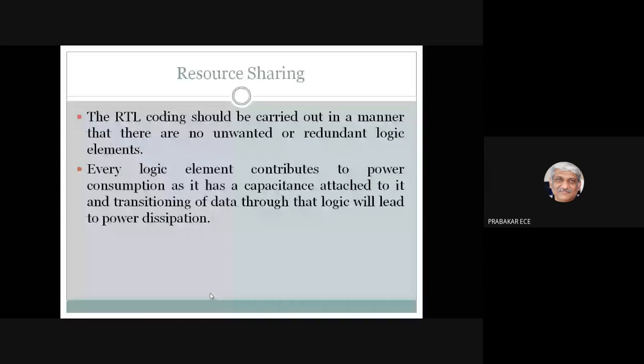And every logic element contributes to power consumption as it has some capacitance attached to it. I think you should know, right? Every line, every track will have an RC component. The resistance and capacitance will be there. The power consumption will always be there. And this capacitance can be considered low in some cases, right? So by having resource sharing, you can reduce the size of your device or your circuit. At the same time, you can reduce the power consumption of the circuit, right? So both the static power consumption as well as the dynamic power consumption will be reduced.